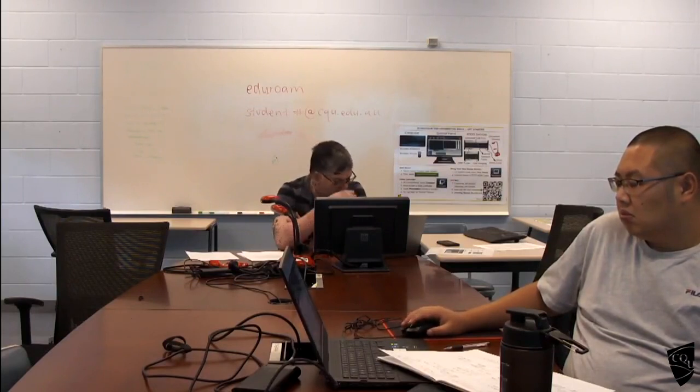If you don't have the support width or column width or beam width, you better take it at the face of the support, or even if you don't have any of those details, you take it at the middle of the support. Those values are higher.